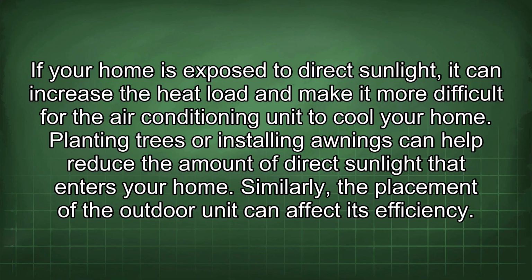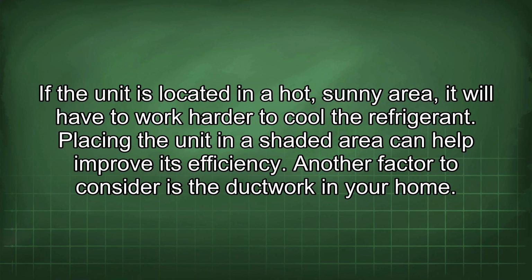Similarly, the placement of the outdoor unit can affect its efficiency. If the unit is located in a hot, sunny area, it will have to work harder to cool the refrigerant. Placing the unit in a shaded area can help improve its efficiency.